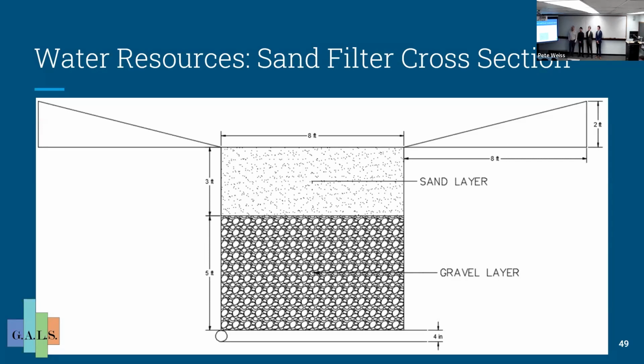I got a question just for Logan, because he threw it out there. We don't often see composite design, and shear studs cost money, right? So what's the benefit? Well, it helps with incorporating the slab and the beam working together with the shear studs. We're only using 12-foot stories, and I didn't know what was going on with the depth of the beams. It minimized the size of the steel beams that we needed, and allowed the beam and the slab to work together. So it provides more resistance. Thank you.